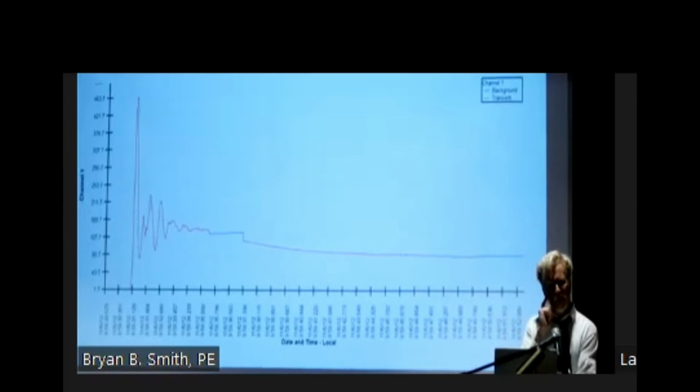I'm like, no one shared with me the pump curve. I always want the pump curve. I want the as-built pump curve. So they're like, whatever, I thought you were the surge guy. It's like, what's with the pump? I'm looking at the pump curve, and I'm like, we're not starting this up today.